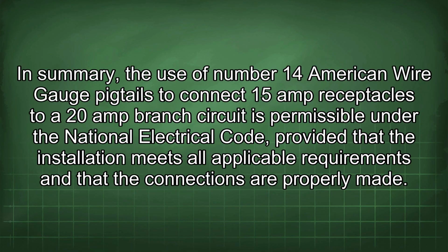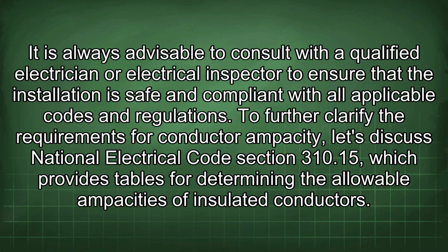In summary, the use of number 14 American wire gauge pigtails to connect 15 amp receptacles to a 20 amp branch circuit is permissible under the National Electrical Code, provided that the installation meets all applicable requirements and that the connections are properly made. It is always advisable to consult with a qualified electrician or electrical inspector to ensure that the installation is safe and compliant with all applicable codes and regulations.